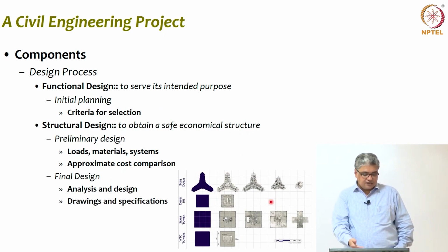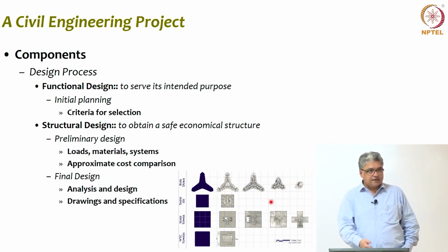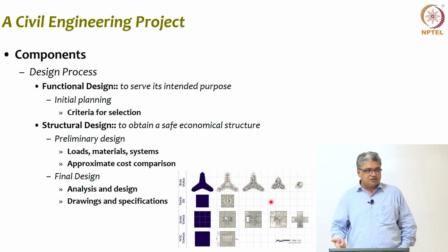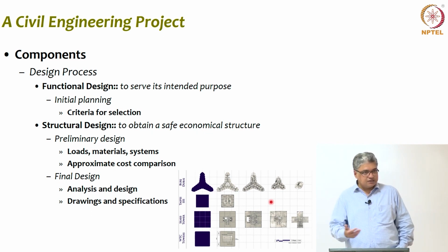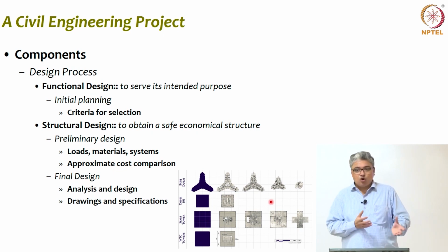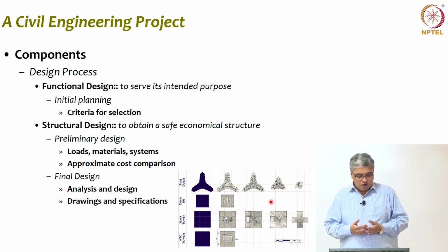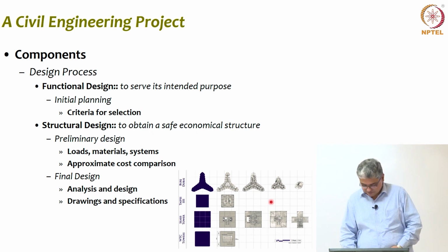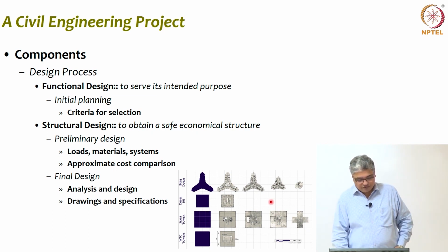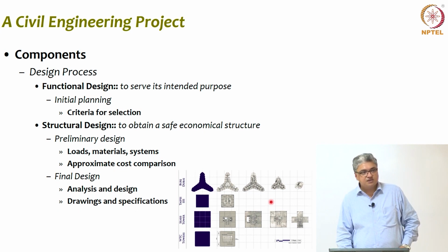And then once that is done, of course you will have the structural design, and in that also it's not a one-step process. It's an iterative process where you first do a preliminary design, you understand systems and so on, and then an important task to be done is cost comparison, because you have to do it in an economic way, right? And this is where again a structural engineer comes in and plays a very, very crucial role in doing this. And finally, once everything is frozen, then you do your final analysis and then finally drawings and specifications.